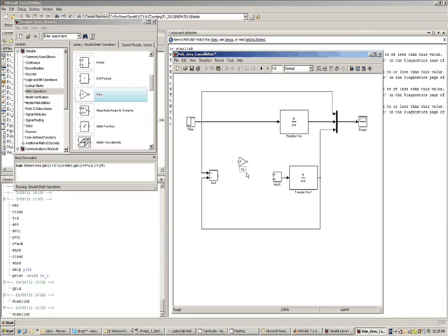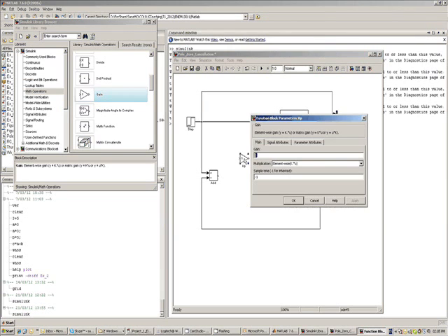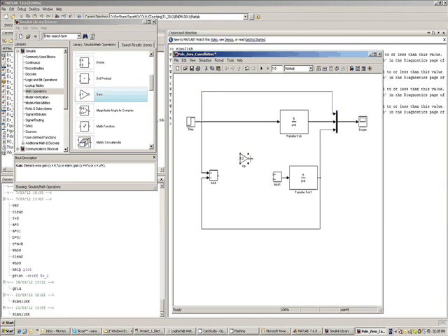So if you double click on the name of the block, you can type anything into that. A new name can be given. So this is my KP. And what is the value of KP? It's 3.2. If you double click on it, you can go into the configuration block, apply the value 3.2, and in fact you can see the value of KP also. Then you could simply connect the error signal into that. So the proportional path is now complete.